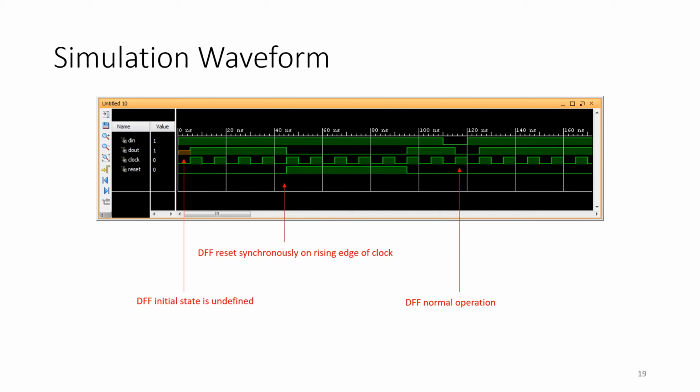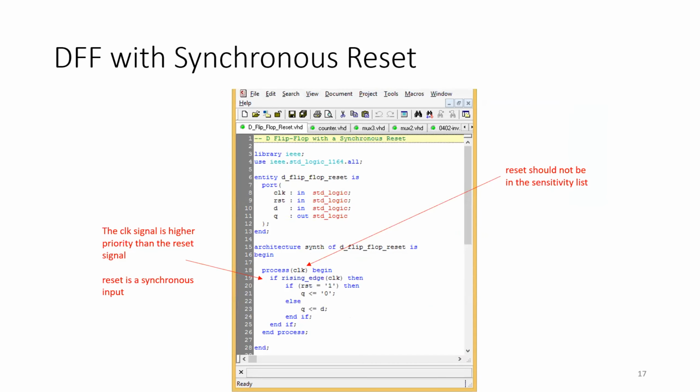So we have 3 programs that would use almost identical test bench. Sometimes I call it clear, sometimes I call it reset. Normally we use the word reset when we have it synchronous. It is tied to the clock.